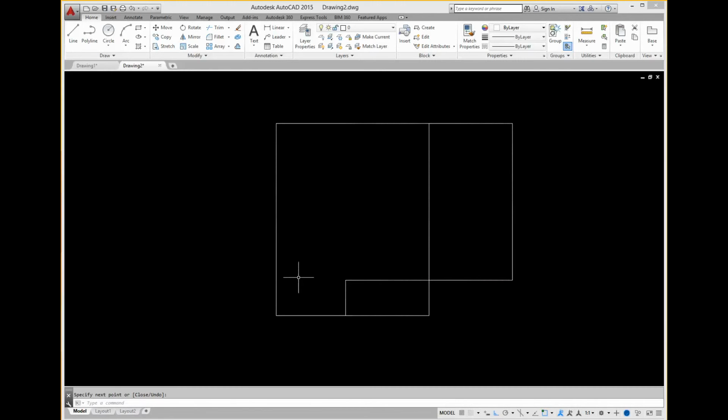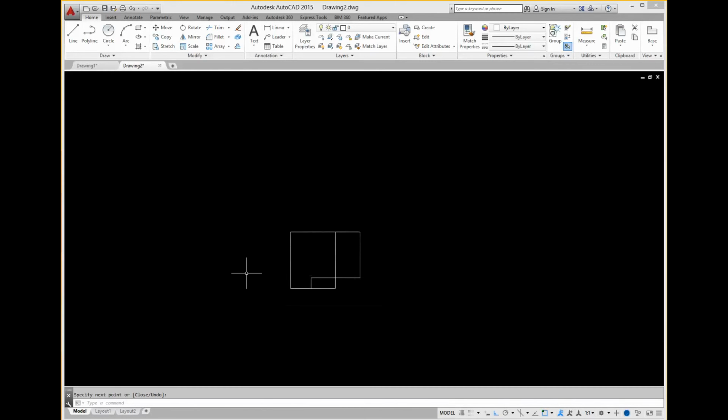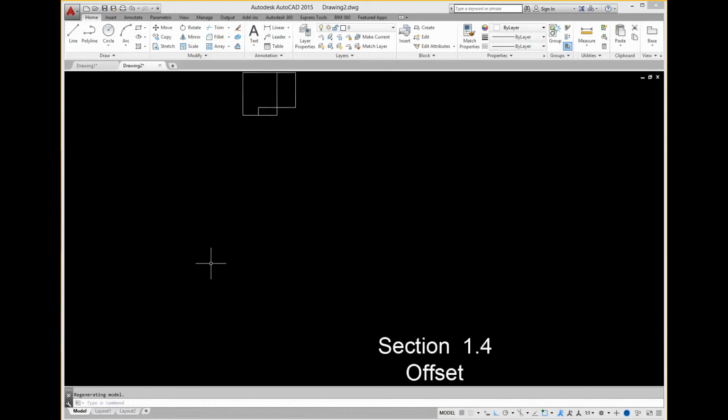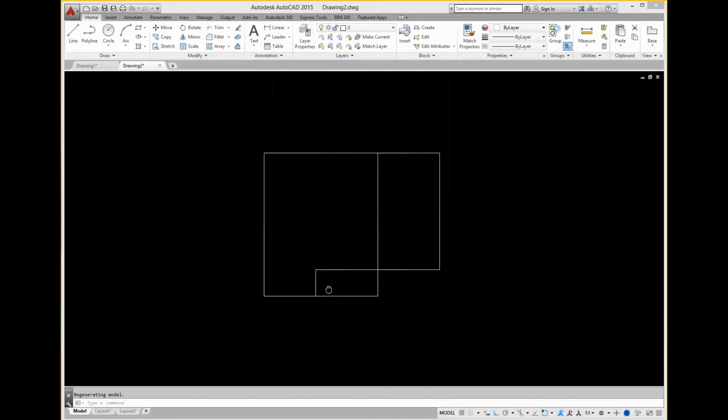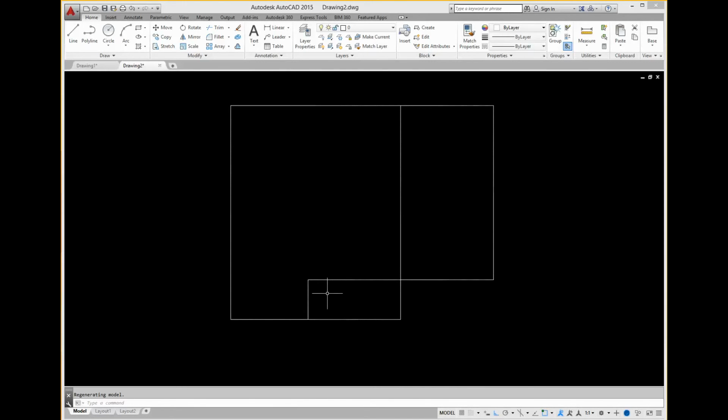So once again, let's look at the zoom command that I was talking about. It didn't work real well the first time. Sometimes AutoCAD gets glitchy and it doesn't do what you tell it to do. But let's type Z and enter, and then you'll see in the command line we get a lot of zoom options. If I type now A, enter, you get the whole drawing coming up and filling up the screen.